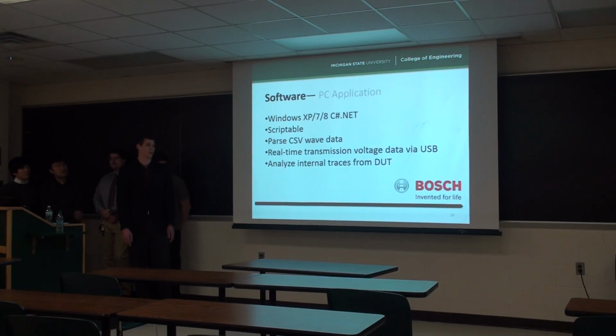And then also after it goes to the microcontroller, it sends the pulses to the MOSFET and we simulate the wave profiles. There's going to be internal traces within the device under test, which is going to be the infotainment ECU and possibly the test bench. And we need to record those within the PC application as well. And moving further, we may possibly be interfacing with CAN or MOST, and if we don't, then possibly next year's design team will. So we need to make it scalable such that we can interface with CAN and MOST buses.